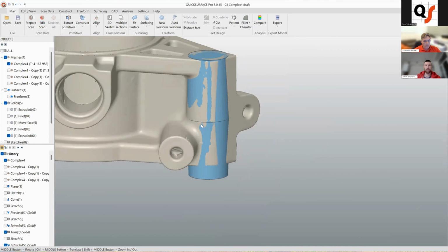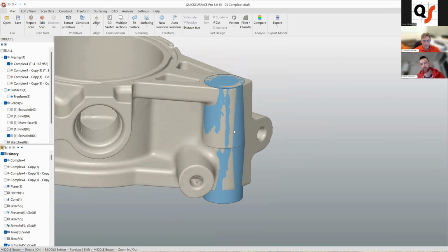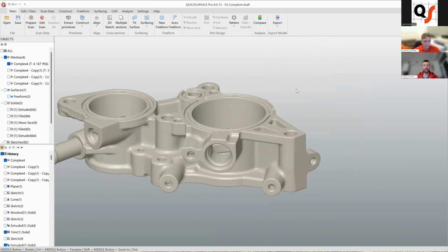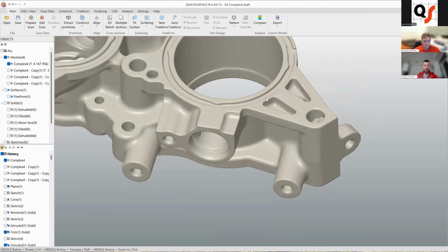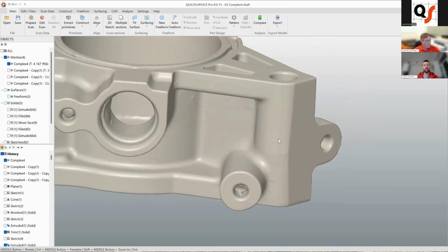So this is how the draft angle finder, let's call it this way, works in our case. And this is the first feature I wanted to talk about. This is super handy in some cases where you have unstable geometries. It's nice to have this deviation control while you're doing everything, so you can just adjust your geometry on the way.